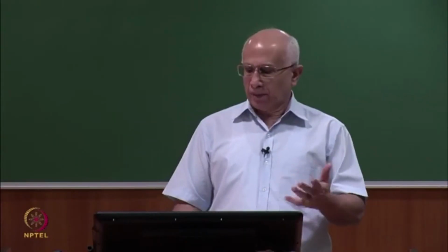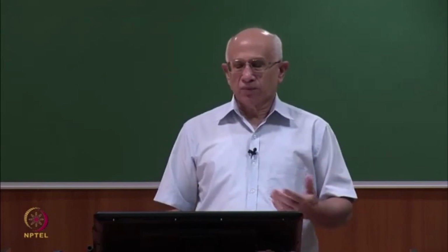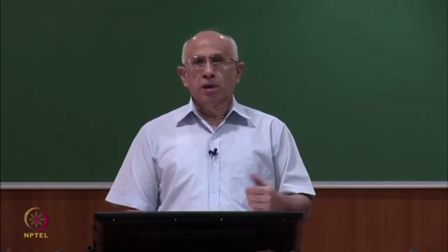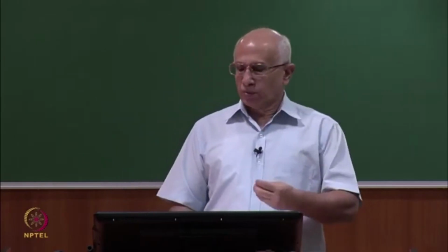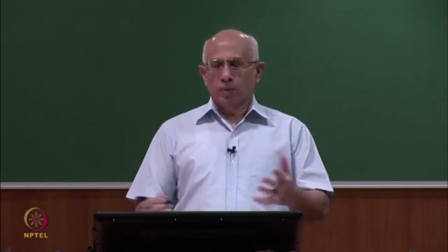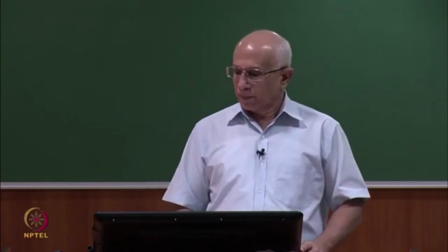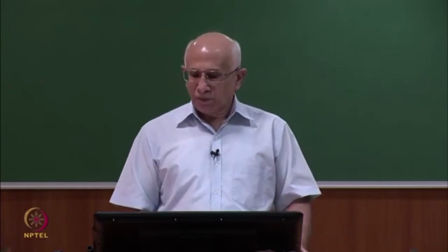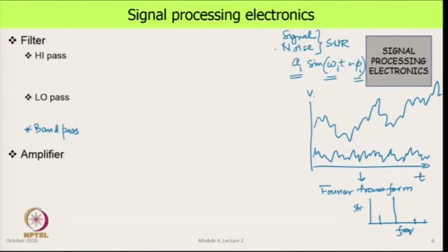Such issues come up in many applications. An example of the last case, where you are looking for a signal in a noisy environment, is remote sensing. We are trying to pick up very small changes in a place where there is a lot of noise taking place. In the context of measurements, we somehow want to get rid of the noise. We only want to look at the signal because that is the strength which is related to the physical parameter we are measuring, and that is the one which we will ultimately get into our data acquisition system.